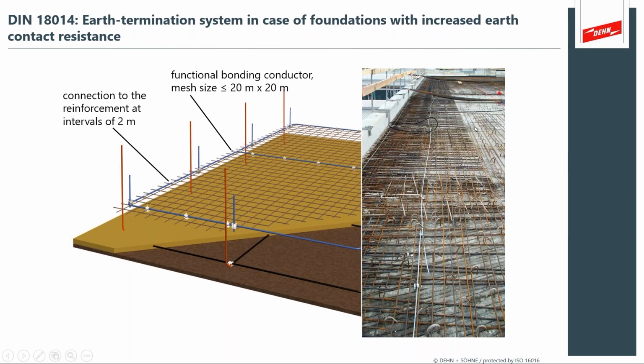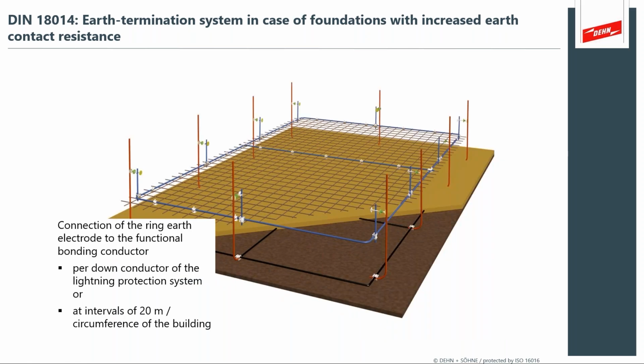In a photograph, you can see now you've got your rebar interconnected with conductors that are for the purpose of conducting lightning currents. Rebar is not a particularly great conductor, so we want to make sure that we're controlling that voltage with conductors that are for that purpose. Then we start adding layers, and these are the connections that in the future you'll need in order to bond to your down conductor system.